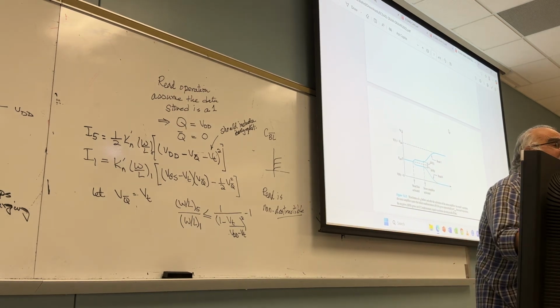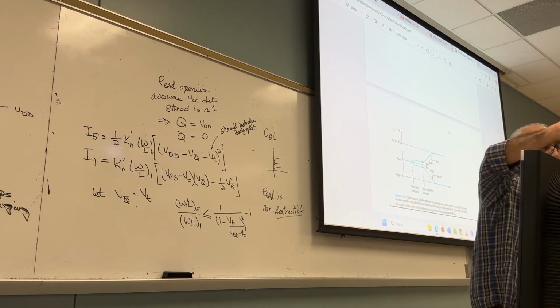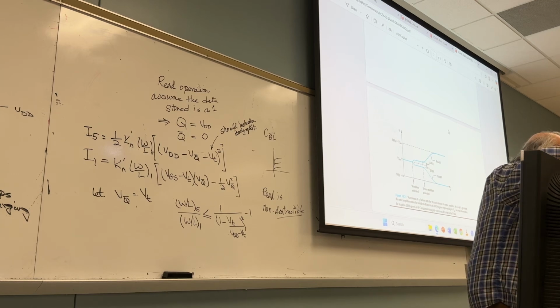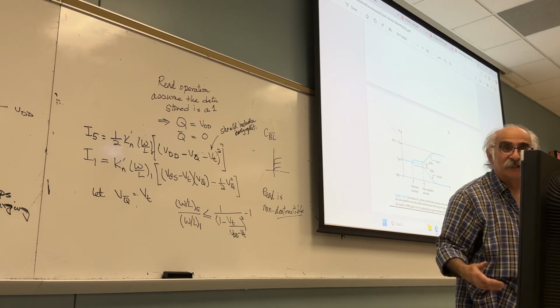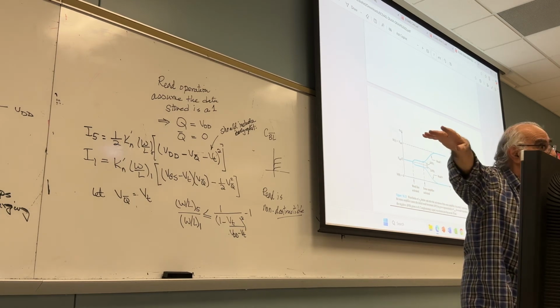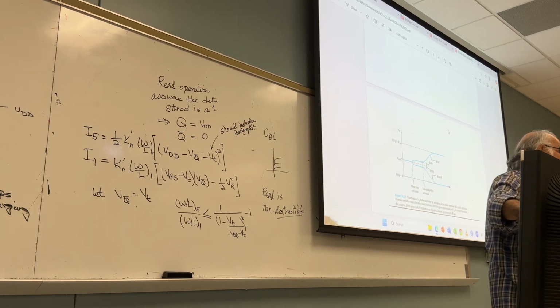Why did I assume here to pre-charge to VDD? Why? It becomes easier to analyze one part of the circuit than both parts of the circuit. Do you agree? Analyze one part of the circuit. Why? Because the other part is not going to work.